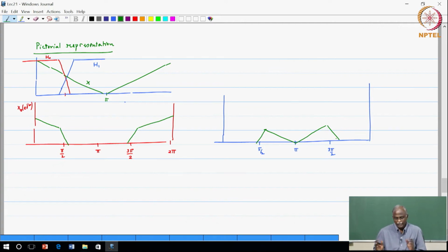So, I have two portions, the two filters have picked off the respective portions of the signal, and these are of the order of 2 pi. The total bandwidth that we are talking about is of the order of pi, so we can do the downsampling by a factor of 2. Again, the sufficient condition is that the net bandwidth is 2 pi over M, where M is equal to 2. The first one has a bandwidth of pi, the second one has a bandwidth of pi. So, I can do the downsampling.